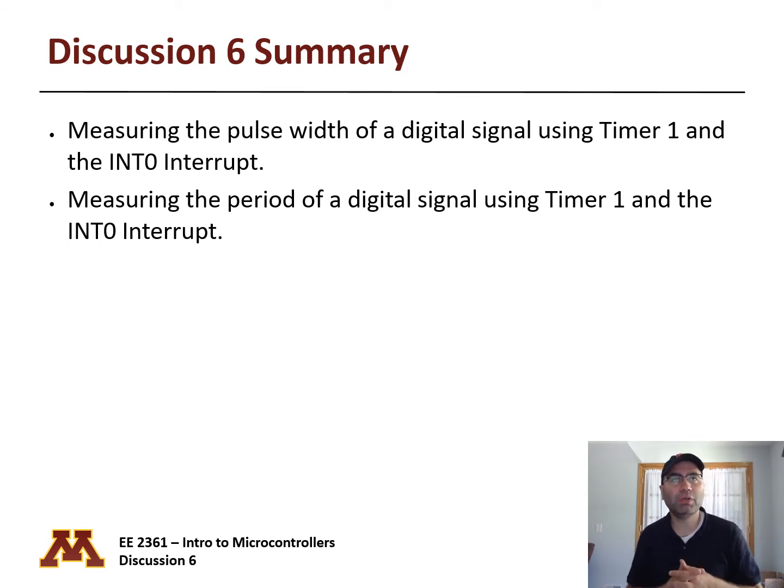In summary, what we are going to do today is measure the pulse width of a digital signal using timer 1 and the INT0 interrupt. You have INT0, INT1, and INT2. Basically, the INT0 interrupt allows you to use an external pin as a source of interrupt, right?